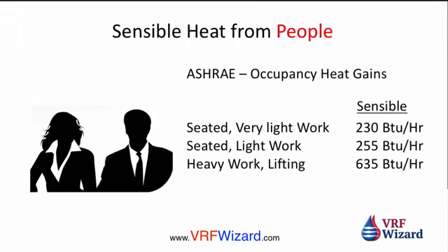So sensible heat from people, basically ASHRAE puts out an occupancy heat gain equivalency, and it's based on the type of activity. So you can see the first one here, seated, very light work, is only generating 230 BTUs. As the level of activity moves up, it's a little bit light work, not very light work, you burn a little bit more BTUs. You give off more heat. If you're doing heavy work and lifting, more strenuous work, then you're burning more BTUs. You're giving off more heat.